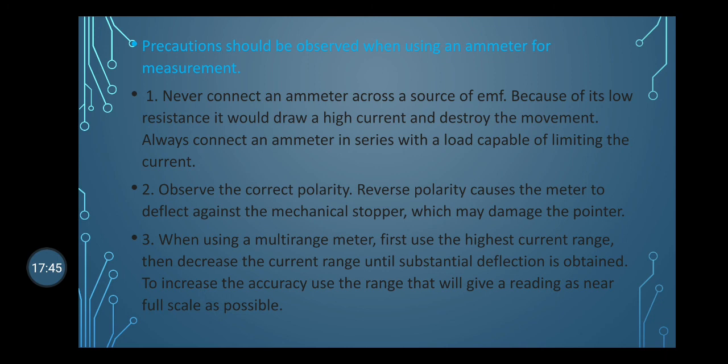If the polarity of the ammeter is reversed, the pointer may deflect against the mechanical stopper, which may damage the stopper, the pointer and different parts of the ammeter.